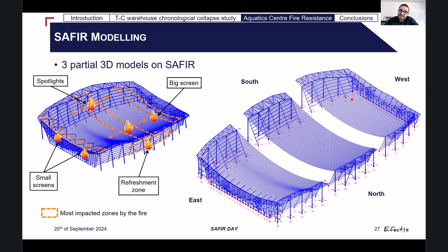The geometry was provided to us by our customer. With such complex structures, sometimes the elements are not linked exactly together. So we used an extensive amount of the same commands in order to link those elements. We also had to use an extensive amount of the relax command in SAFIR because we wanted to take into account the stiffness of the connections.